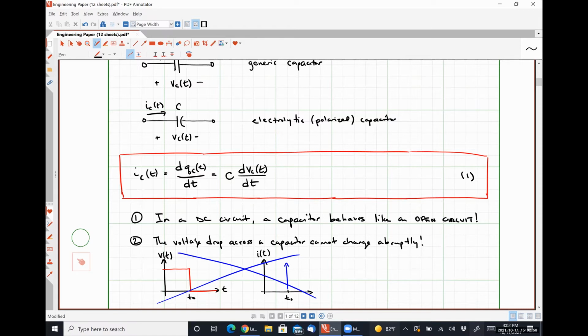So just to try to burn this into your heads, because it's going to become critically important as we are talking about transient analysis for the next week, starting on Wednesday. The current through an inductor cannot change abruptly, and the voltage across a capacitor cannot change abruptly.